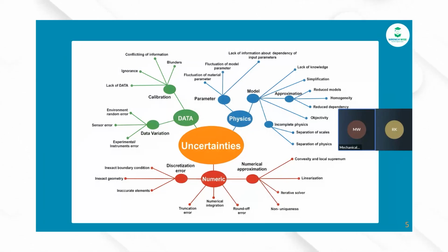Experimentally, generally speaking, with CFD, we often validate against a lot of experimental or test bench data. So if pitot tubes and thermocouples are used in the experiment, and you have at least around 5% error in between, this is still considerable, saying that CFD has reached close to what the real scenario is.